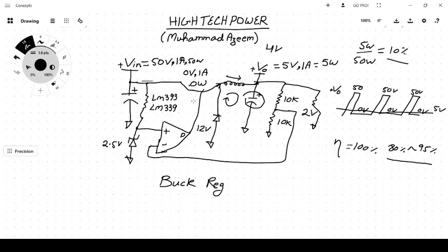We saw how the linear power supply or the linear regulator was dissipating much higher power, and for that purpose we had to use heavy heat sinks. When we shifted gradually by inserting a resistor and then the inductor and then the freewheeling diode, we saw how the efficiency increased to ideally 100% and practically 80 to 95%, and there was no inrush current to the output capacitor, and the output voltage is again well regulated. So this is the advantage of using the switching regulator or switching power supply.